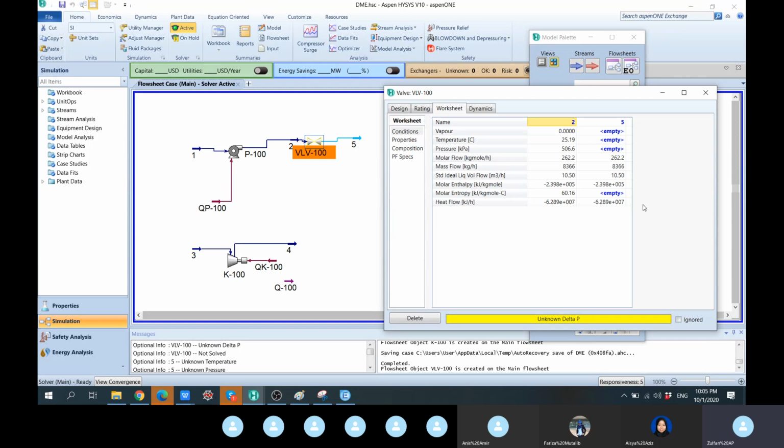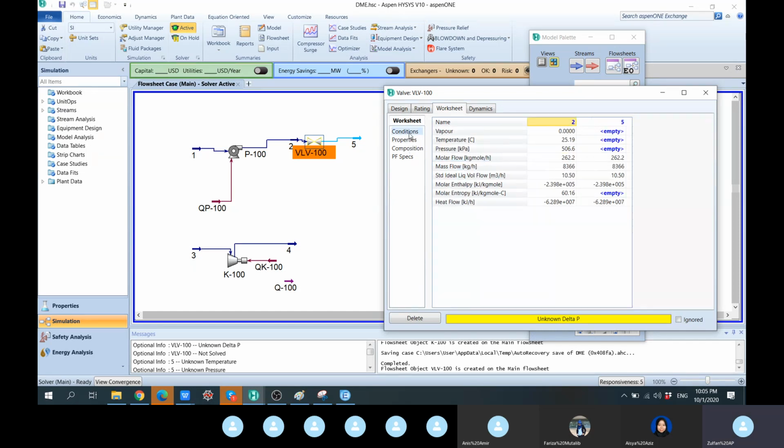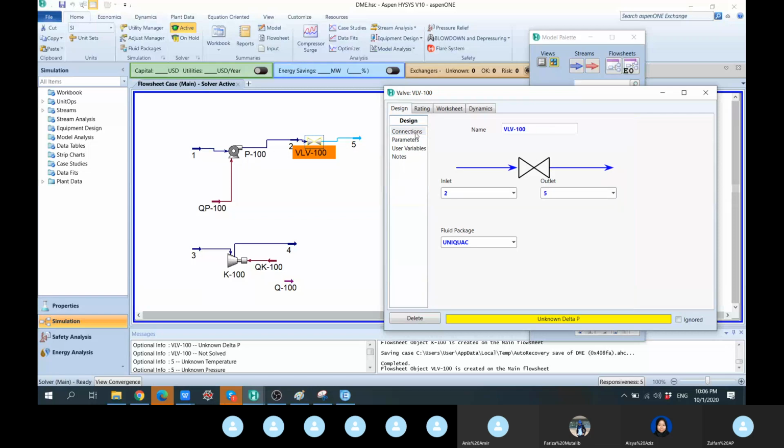So let's go back to this. We have the flow rate already, so that is gone. What is missing is CV, delta P, and specific gravity. In this case, specific gravity is already there, since the density is there. What is missing is CV and delta P, so we can specify either CV or delta P. In this particular case, they say it's delta P, which helps a little bit. Design parameters, so just put delta P.